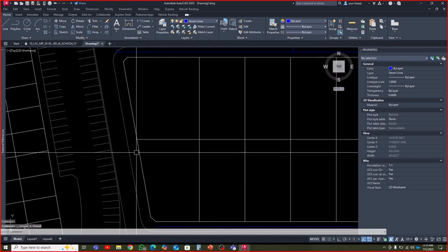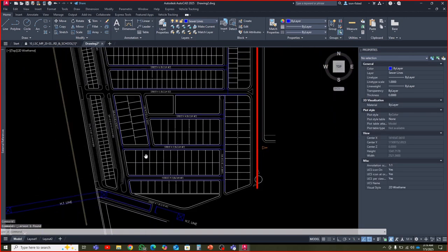Okay. So make sure there are not any looped connections because SewerGEMS can't process loop connections. These are going to be treated as pressurized networks, so we are not going to be analyzing any pressurized network in SewerGEMS. This doesn't fall in the capability of SewerGEMS.